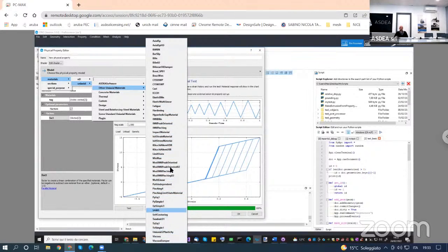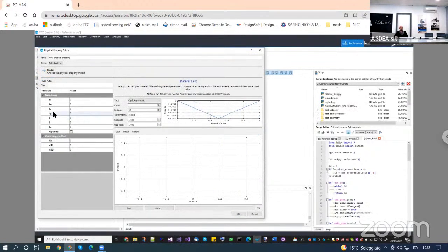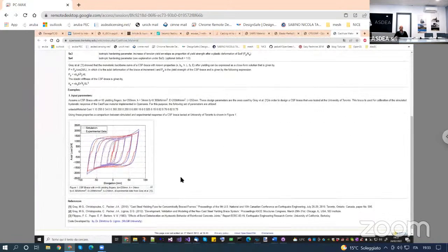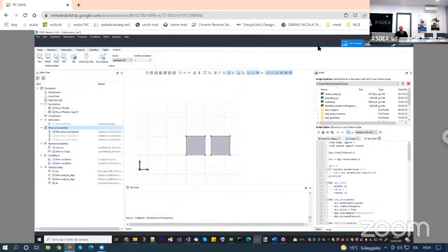So, no, I don't know what the cast material is. No. Let me see. Otherwise, if you have some experience, because you said that you simulated it with another software. Yeah, the main thing is I have two experimental tests, one for the pipe with T joints, and I need to define the joint using OpenSees. One reference study I found uses a zero length flexural hinge, and for the pipe they're using an elastic beam column, and they are matching the experimental test. But in the case of the anchor bolt, I'm using many elements, but it's not giving me the results. But in SAP2000, when I use the multilinear link element with the pivot hysteresis, it's giving me the exact value. So I was not sure whether it would be correct or not.